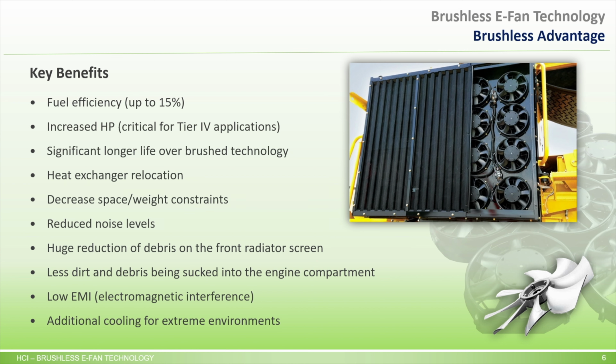Significantly longer life over brush technology. Brushed fans typically last about 5,000 to 6,000 hours. Brushless fans will last about 30,000 to 40,000 hours at full speed, but you almost never run these fans at full speed. We talked about ease to relocate already, decreased space constraints, reduced weight, reduction in noise levels. These fans are only running at a percentage of their maximum speed.